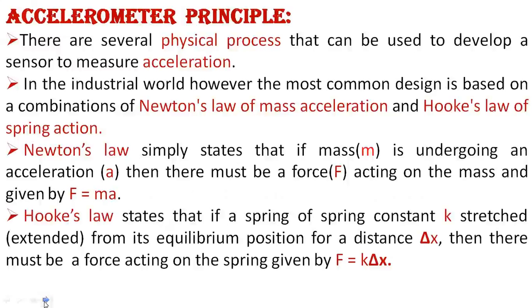Next one is the accelerometer principle. There are several physical processes that can be used to develop sensors to measure acceleration. In the industrial world, however, the most common design is based on the combination of Newton's law of mass acceleration and Hooke's law of spring action.